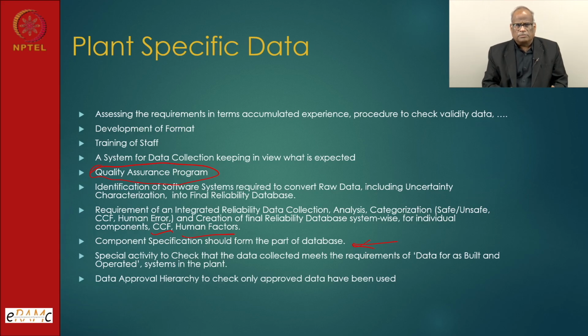Then, specific activity data are fault, build and operate. So, what kind of failure modes we are looking for, only that failure mode should be chosen, or data should be collected. Suppose we do not have information on failure mode, conservatively all, we will see in the next slide what kind of options we use. And the data collection procedure should be approved at the highest level in the management and should be followed.